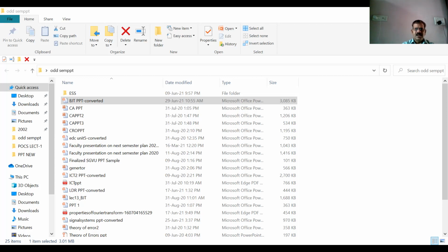Total emitter current does not reach the collector terminals because a small portion of it constitutes base current IB. So IE equals IC plus IB. Also the collector diode is reverse bias. So very few minority carriers pass the collector base junction, which actually constitute leakage current ICBO, which is a very minor current in the range of nanoamperes or microamperes.